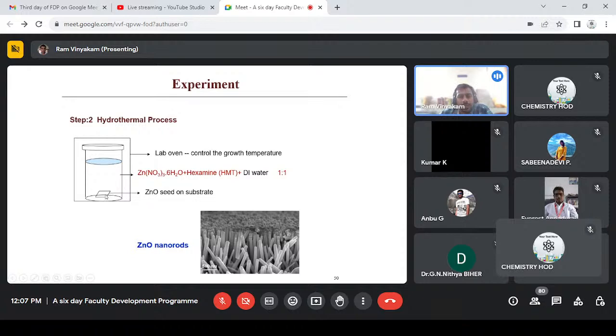And for the seed layer, if you have the feasibility, you can grow it by any solution process. In our lab, we use an all-solution process by means of spin coating. We create a zinc oxide layer. In most other cases, they use sputtered ZnO as a seed layer, and you can take just a dip-coated ZnO as a seed layer too.